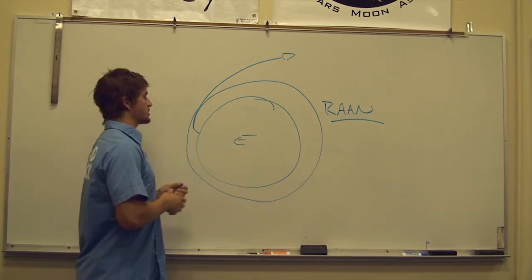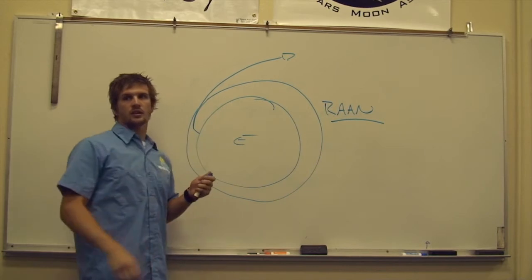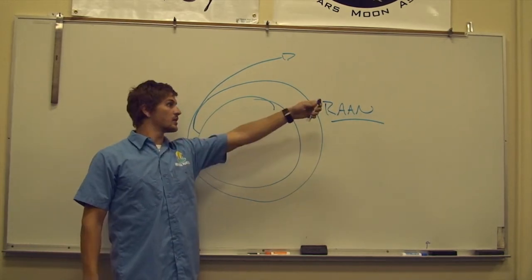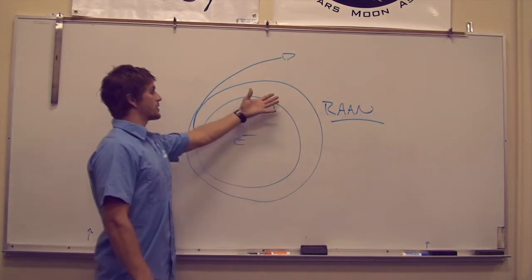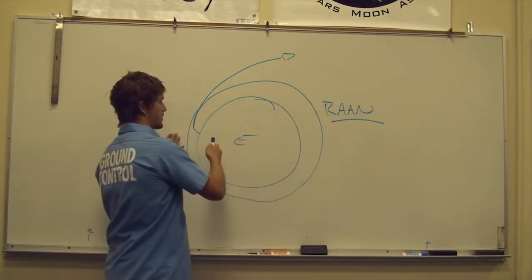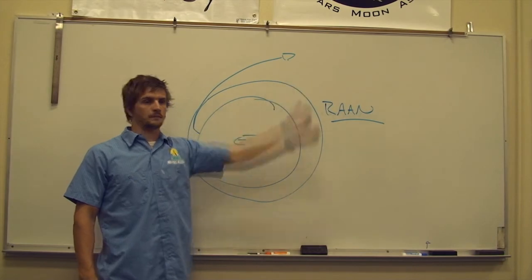And then our coast time, which is the time that we spend orbiting the Earth here, will adjust the apogee of the transfer orbit to include the Moon. And essentially both methods now have us into our next phase, which means we are off the Earth, and now we are ready to start our trajectory towards the Moon.